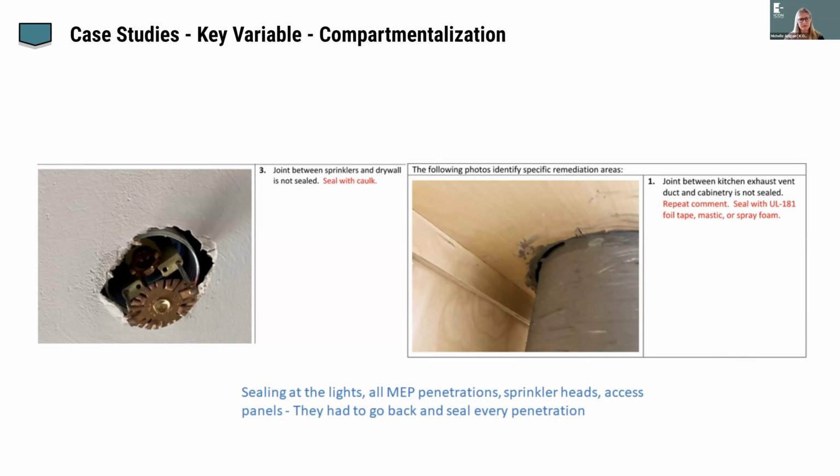It's not uncommon at all. There are things that penetrate the ceiling assembly, the floor ceiling assembly, which is not only an important air barrier, but is also an important fire rated separation in a multifamily situation. So sprinklers, conduits, ductwork.